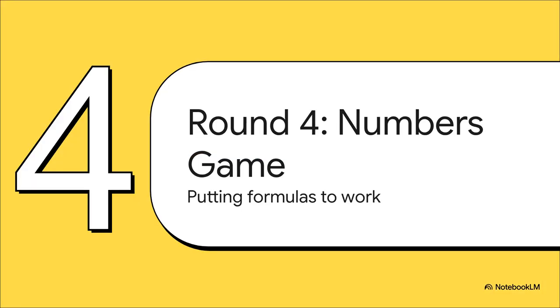Time for round 4, the numbers game. Let's do a quick calculation. Let's say you need to find the capacitive reactance, Xc, for a 10 microfarad capacitor on a 50 Hz supply. First, you write down the formula, Xc equals 1 over 2 pi Fc. Then you plug in the numbers, but be careful. You have to convert 10 microfarads into 10 times 10 to the minus 6 farads. Punch that in and you get about 318 ohms. Remember the process: formula, substitution, then a nice boxed final answer with the units. That's how you get all the marks.